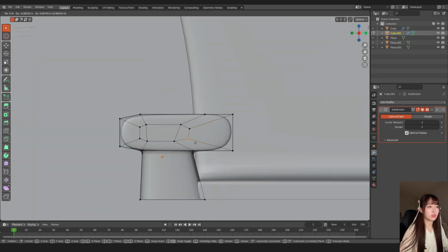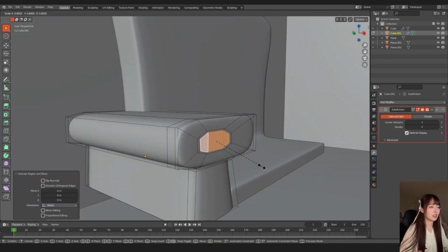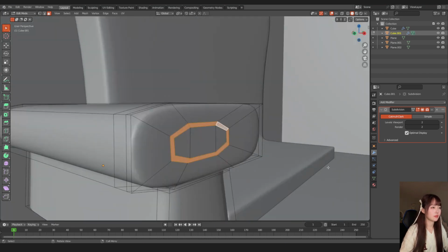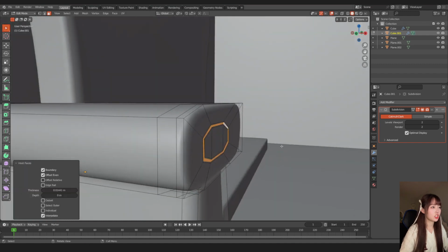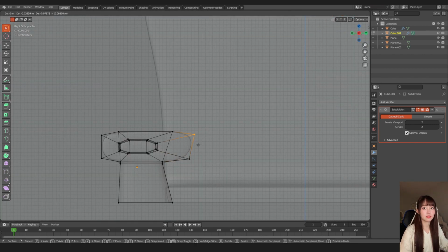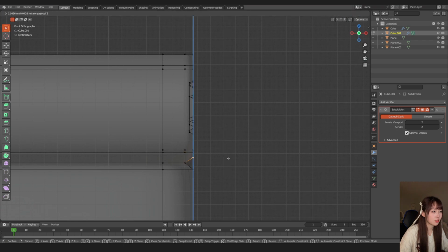I'm going to just quickly do an oval shape, which is some detail in the concept. Just hit E and right click so we get another face and then scale it down. Extrude these faces. Inset actually. I, inset, and then G, X. Just move the line inside this area a bit up here. Select these two here and move it to the right.